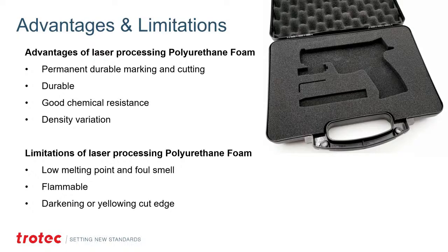It does have a low melting point and a foul smell, but that's like any polymer when processing with your laser. Typically the smell, even outgassing after you take the products out, will last no more than a day or two. After that, the product is clean smelling. So just try not to deliver to customers immediately afterwards if that's going to be a problem.